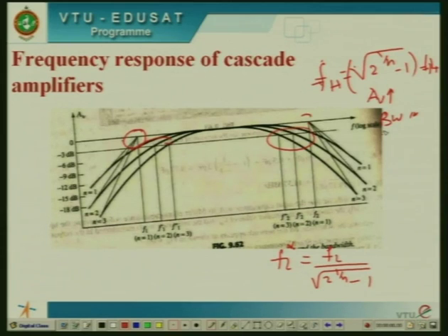stage amplifier. The input impedance of the multi-stage or cascade amplifier is that of the input stage of the first amplifier, and the output impedance is nothing but the output impedance of the final stage. Therefore, without affecting the input impedance and the output impedance of an amplifier, the gain of the amplifier is improved and the bandwidth of the amplifier is improved.